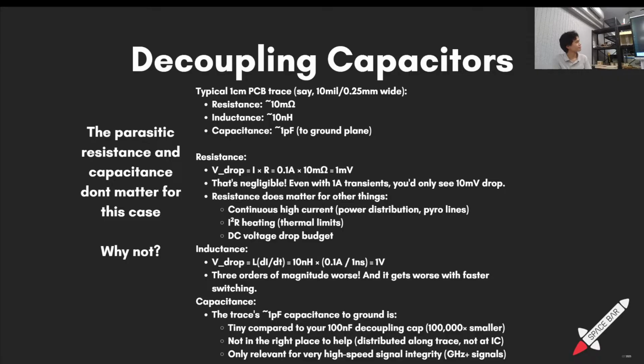these signals have sampling periods. They sample during a predefined period of time, and the signal has to be ready by that time. But because the line is imperfect and you have high capacitance, it turns the nice sharp edge into this, and it may not be able to meet the proper static discipline by the time.